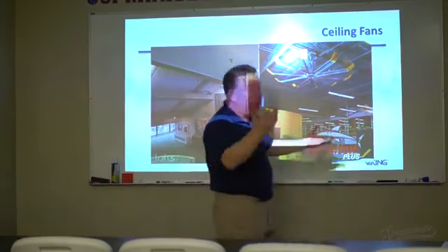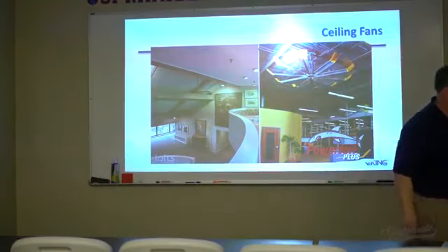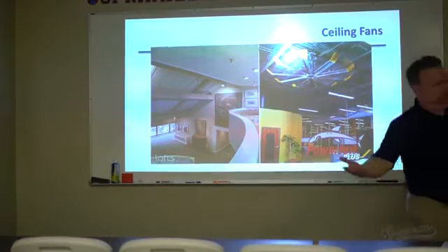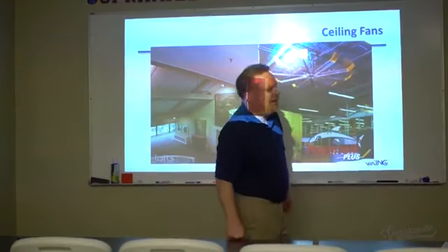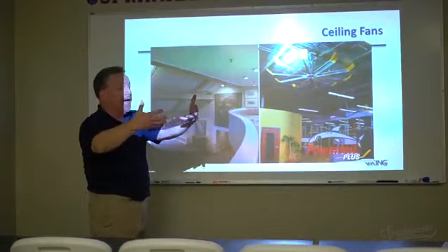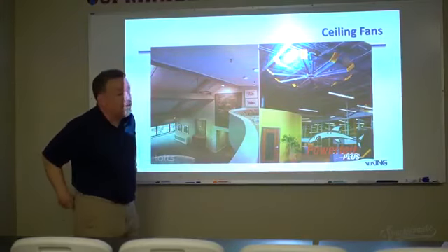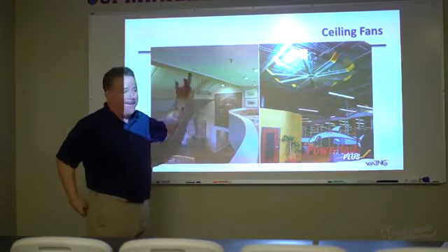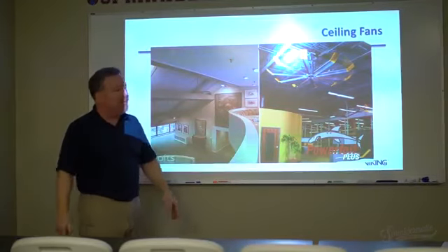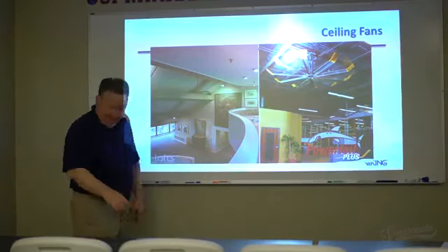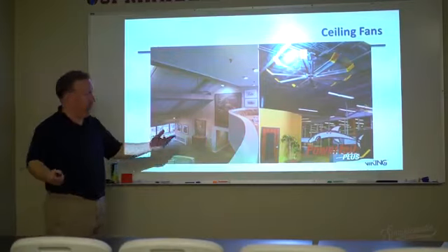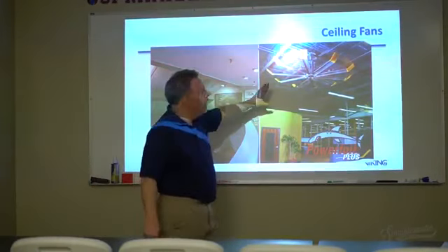The other problem is, what if Joe's just decided to do that anyway? You don't give a permit for that. If we change occupancy, that's a good time to catch all that stuff. But maybe they just decide they're going to go with this new theme. You may not get a change of occupancy, you may get a change of use. Odds are you're not going to catch it until an annual.